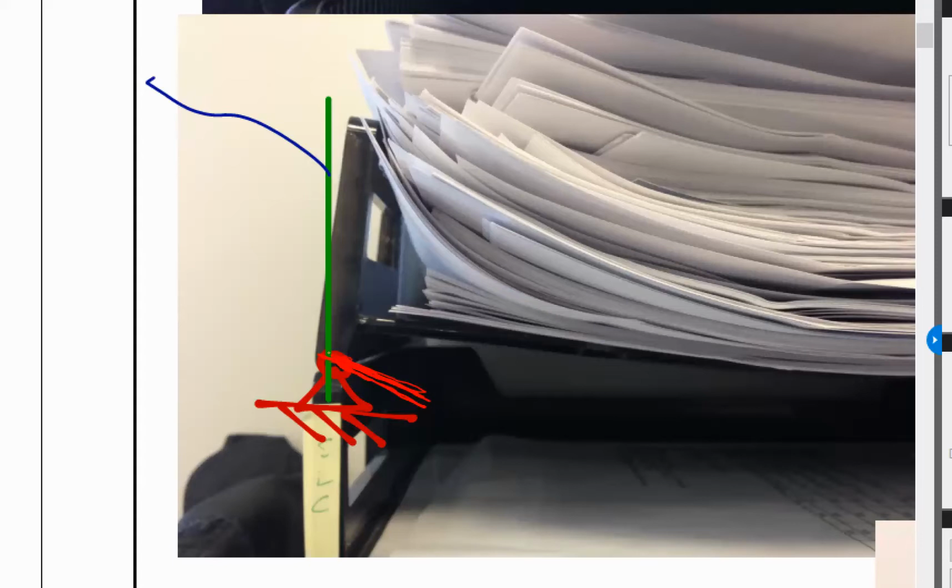And as it rotates, it creates that curvature right there. So that tells me that it's pinned. Now we know that if it was fixed right here, then it would have that straight, then curvature, and that straight segment would form a 90-degree angle, right?